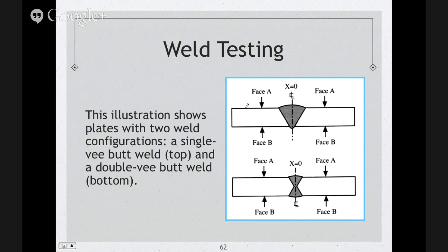And you would put your transducer here, right? And what you would do is you would shoot at an angle into your weld, and as you move this transducer back and forth, you'll be inspecting different sections of your weld, depending as you start moving back and forth, right?